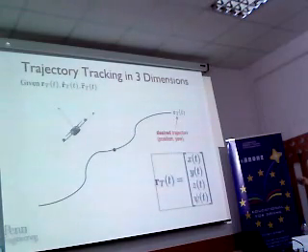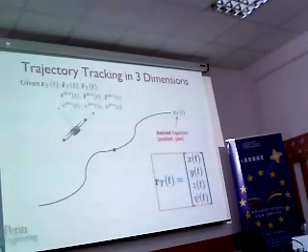Right? So now the controller has to calculate the forces F1 to F4 in order to follow exactly this trajectory. It means that it will correct the x, y, and z so the quadrotor follows exactly this function of x, y, z, and yaw. We want this 4-dimensional vector to be differentiable, and we want to be able to obtain not only its derivative, but also its second derivative.